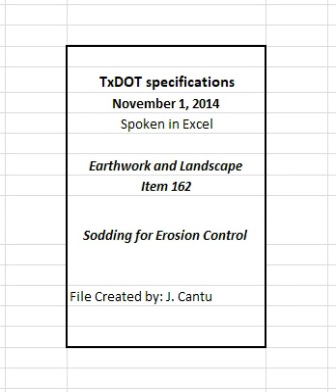Plant the sod specified and mulch, if required, after the area has been completed to lines and grades as shown on the plans. Apply fertilizer uniformly over the entire area in accordance with Article 166.3, Construction, and water in accordance with Article 168.3, Construction. Plant between the average date of the last freeze in the spring and 6 weeks before the average date for the first freeze in the fall according to the Texas Almanac for the project area.